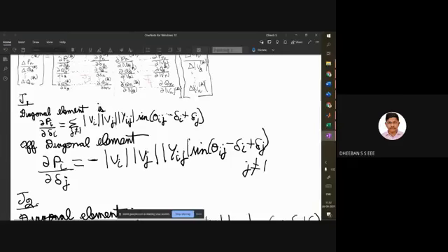Can anybody justify why you are not having a summation in your off diagonal element? Sir, because the value is, for example, y12 and y21, both are equal. Yes, of course. Only self-admittance, we will add in the individual buses, y12, y13, etc. Yes, you got the answer right.